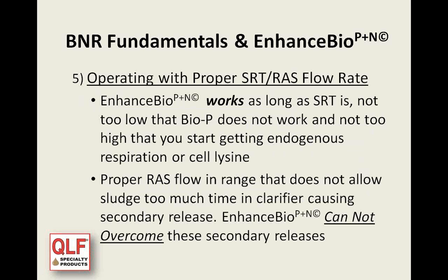Number 5 is operating with the right SRT and return sludge flow rates. EnhanceBio will work as long as the SRT is within the proper operating ranges. If you get too low with your SRT, you won't get BioP to work. If you have too old a sludge, you actually have endogenous respiration or cell lysis, and then you have phosphorus going back into your system, which is another secondary release, so to speak. And it gets a little bit more difficult for us to overcome that type of situation.